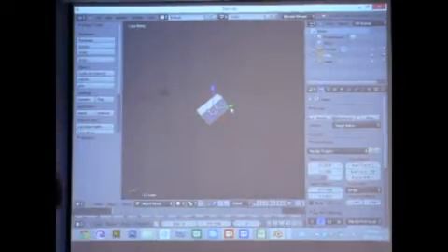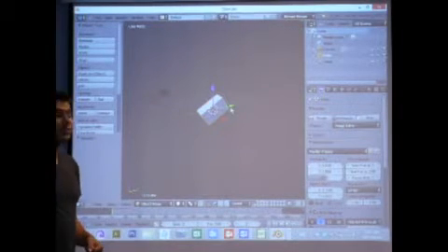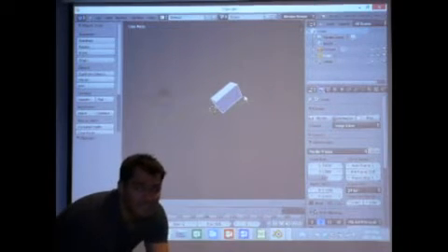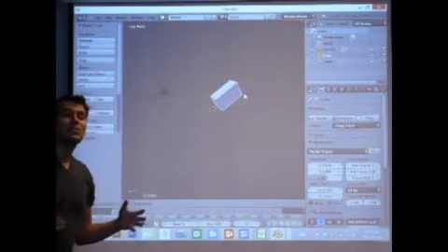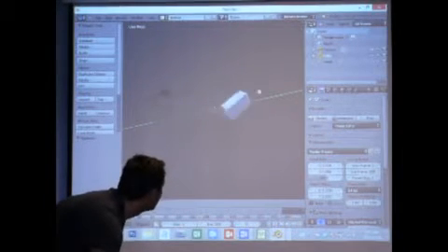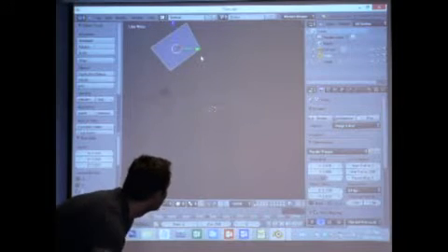And lastly, of course, we want to move objects in different directions, so you do that with G. You press G, and you can move it around your scene. And of course, X, Y, and Z will control the movement. So if you want to move just in the Y direction, you press Y as you're moving it, and move it along the Y axis. Z, and the Z axis.